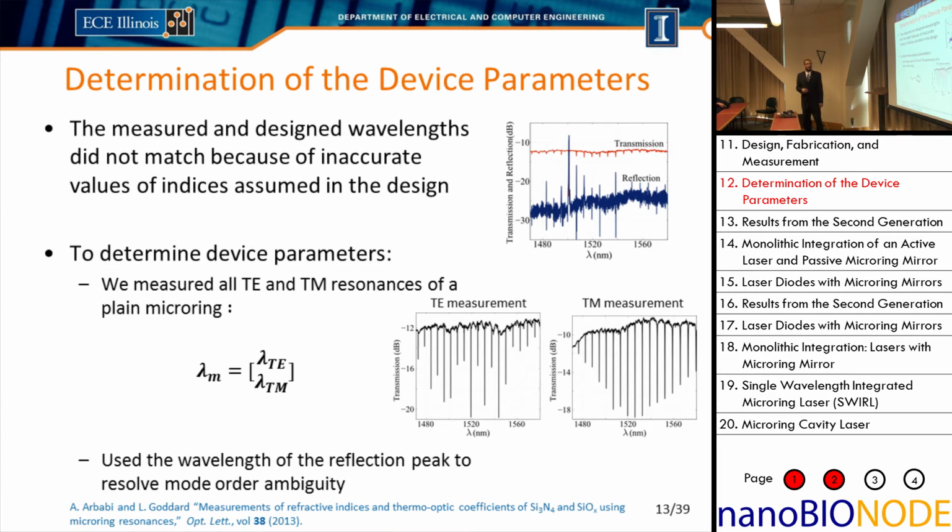Well, one thing to notice is that the resonance wavelengths depend very critically on whether the light is TE or TM polarized. So you get different effective indices for different modes of propagation, and based on these resonance locations, the difference between TE and TM, and also the geometry, the free spectral range, which is the separation between adjacent resonances, the free spectral range plus the TE and TM dependencies, these determine where the resonances line up. So we measure for a single microring resonator the positions of these resonances, and from this we can infer the refractive indices of the core and the cladding material.